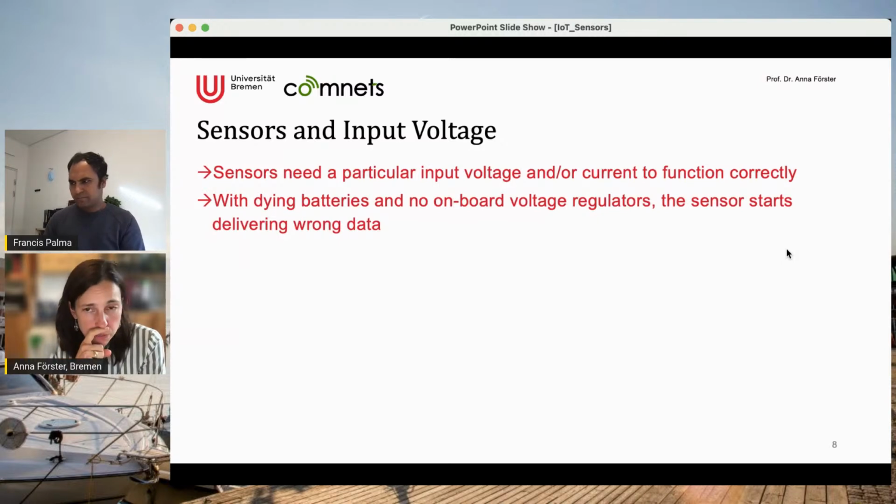This is very important because most of the components on board will continue working also with lower voltages, and that goes for quite a long time. They will not simply switch off at some point, but they continue trying and trying and trying. And some very weird side effects arise.